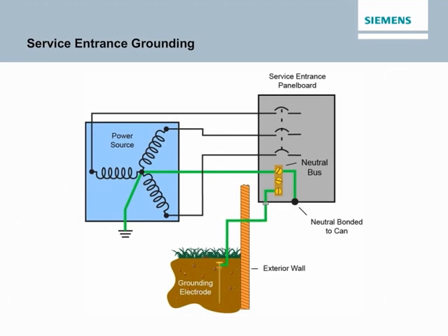The panel board neutral conductor is grounded only at the service entrance, never at any downstream equipment. In the accompanying illustration, the neutral is grounded at the service equipment by connecting a conductor from the neutral grounding conductor to a grounding electrode. The neutral and the panel board enclosure are bonded together at the service entrance so that the enclosure is also connected to ground through the grounding electrode connector. Bonding permanently joins metal parts to form a low resistance path for electrical current.